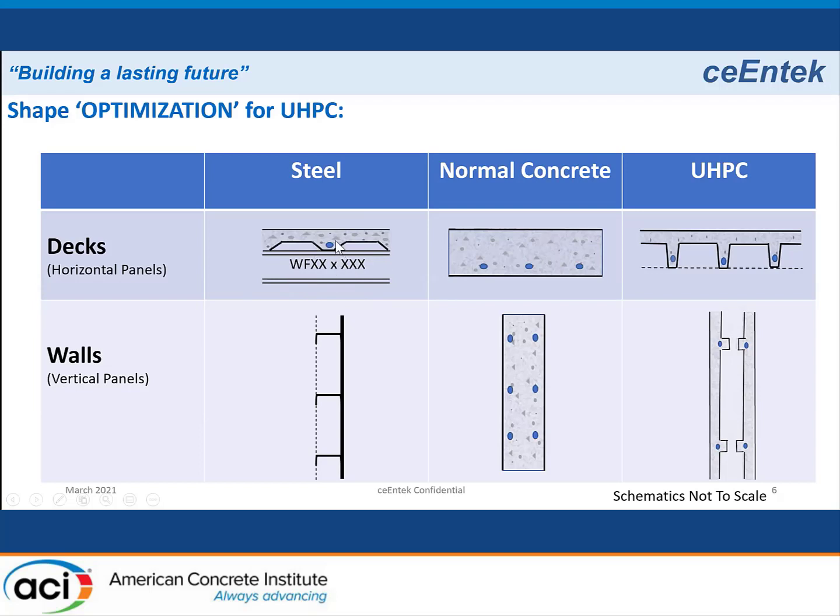We put some rebar in the corrugations, and we put some concrete on top. So a steel deck looks typically like this. The steel wall panel is very similar. You have a thin plate. You have some purlins and beams, two directions to stiffen it up. This may be 2 layers of steel with some insulation in between if it's an insulated steel panel. So again, you see a thin plate with some stiffeners in both directions.